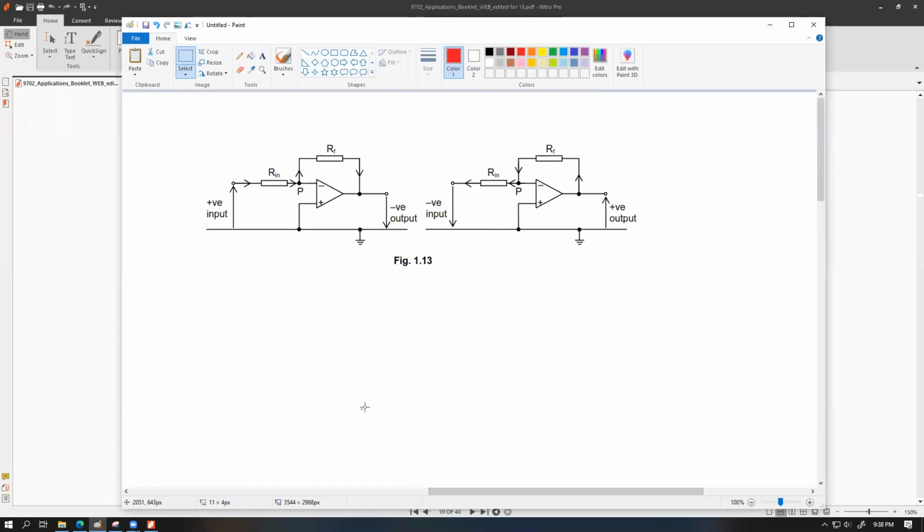Okay, something like this. Let's say at this point the voltage of this exact point is 0 volt, and the voltage of this exact point is 0 volt. So what you can see is that in this case, this is the high voltage. So I can write the current flow through this pathway is same all over. That's just Kirchhoff's first law. You cannot have different current flow through this pathway.